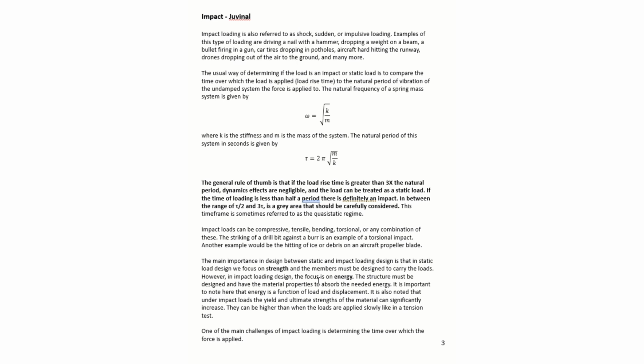And energy is a function of the load and the displacement. And so if you have a very rigid material that is very stiff, when it sees a load, it's not going to deform very much. And if it doesn't deform very much, it's not going to absorb a lot of energy. And it will pass that energy on to other parts of the system, or for example, occupants in the system, and that's where impact loading can become dangerous.